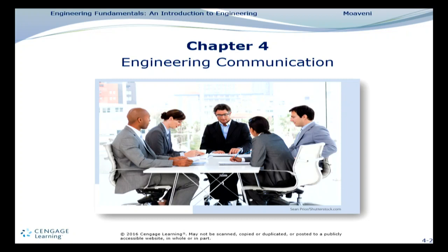Oh yeah. Well, the other one is I worked with a process unit where the person who designed it did not think about the orientation of the actual vessel. The manway was put in between the two vessels, and the vessels are spaced 8 inches apart. So we had to flip the vessel over and install it backwards to make it work, because they did not do 3D thinking.